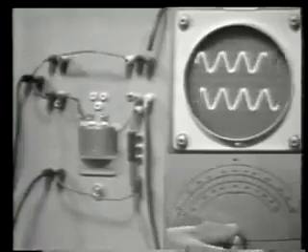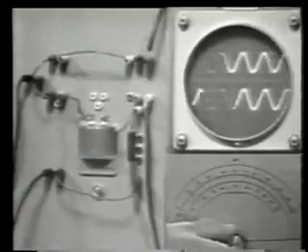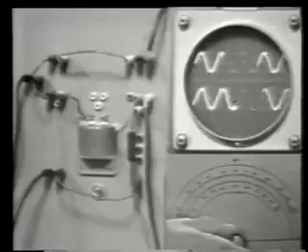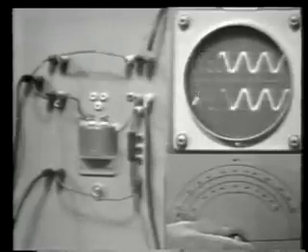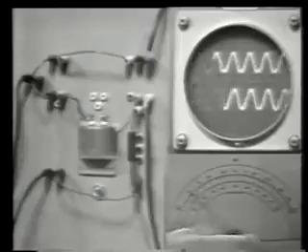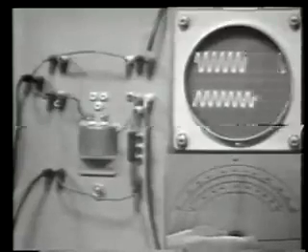Now you'll notice down at the low frequencies, I'm down around 200 hertz now, you'll notice that I do have an output. I have 10 volts on the input directly from the signal generator, and on the B trace, the lower trace, I show 10 volts of output from my filter circuit. So we're passing the low frequencies because this is a low-pass filter. As I increase the frequency, though, you'll note that at about 600 hertz, the output starts dropping off. Now we're beginning to reject higher frequencies, which again the low-pass filter must do.